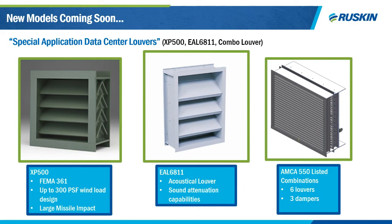This model is also adjustable, so it can be modulated open or closed based on the desired system pressure. We have several acoustical louver models, but this is our most economical acoustical louver model with a free area of 30%. And if an acoustical louver alone is not enough to attenuate that noise, Ruskin also provides an extensive line of silencer products that you can combine with either your damper or your louver to mitigate that noise further.